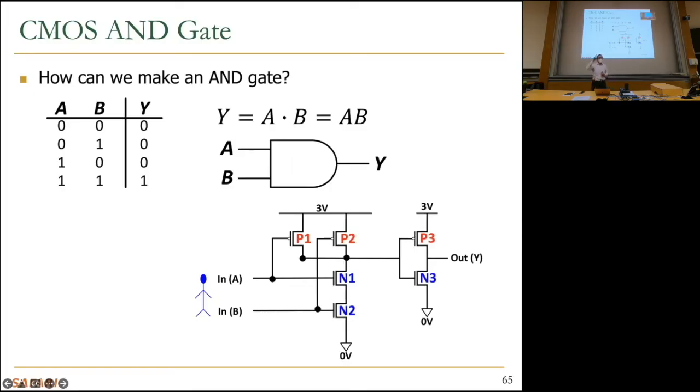But you have to put the NMOS transistors up and PMOS transistors down, and that's not going to work in CMOS technology. Make sense? Basically, in CMOS technology, PMOS transistors are good conductors of high voltage. They're very poor conductors of low voltage. If you put them down, they're not going to pull down the circuit because they don't work that way. That's the operational principle of PMOS and NMOS transistors.